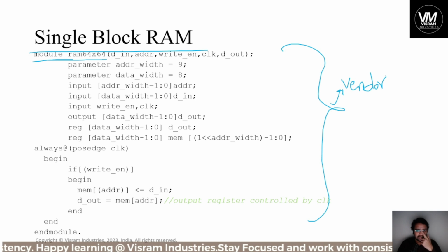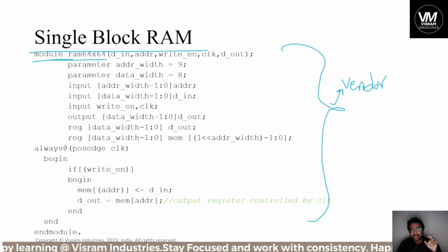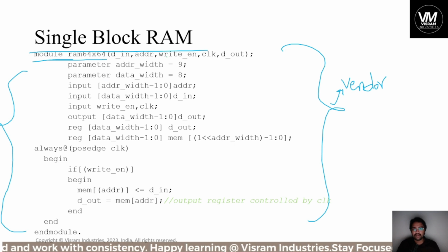user guide manual, and in that user guide manual, with the limited BRAMs listed, there will be some specific BRAM Verilog HDL code, some basic sample Verilog HDL code that is written to declare the functionality of the BRAM. So this is how it is declared. This entire BRAM is declared. You have to mention input data in, address, write enable, clock, D out.